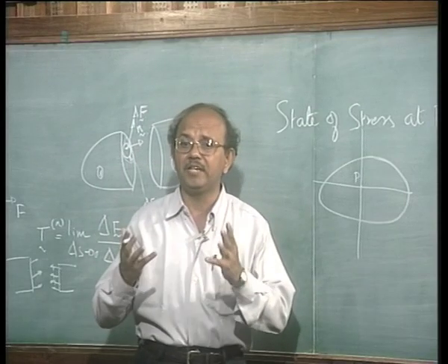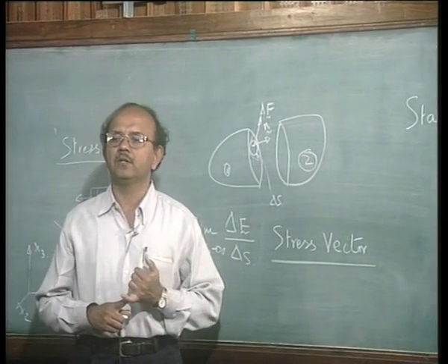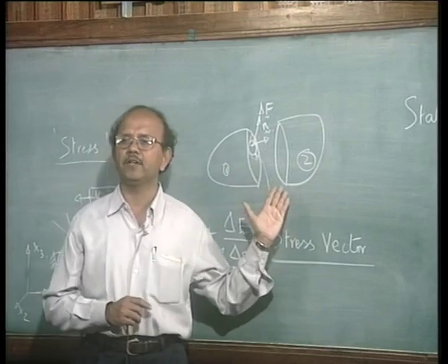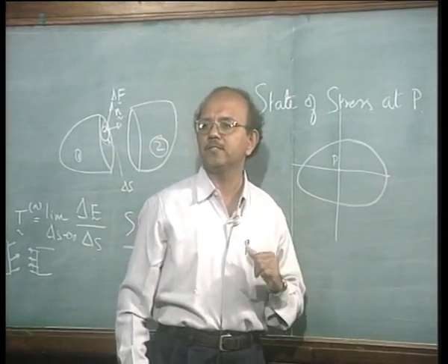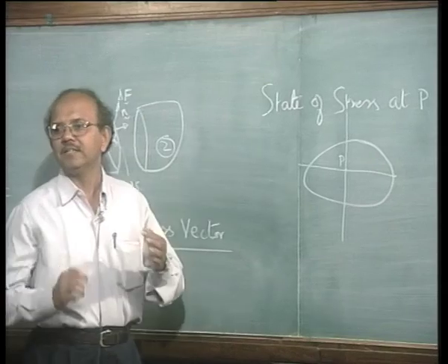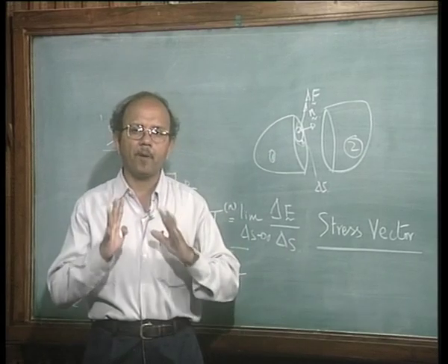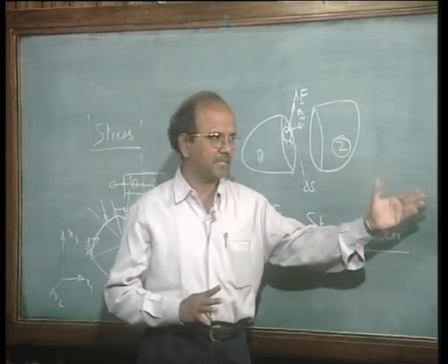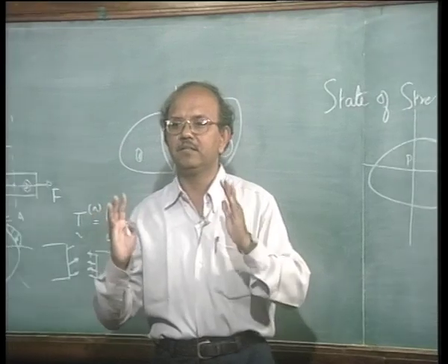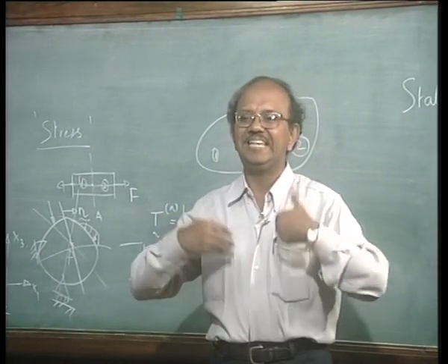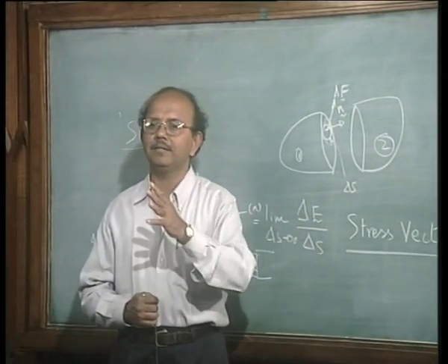So these 3 planes are well defined planes, okay, and the first thing I will do is, I know that it is difficult to define it in infinite number of planes. So as a first step, let me define them in these 3 planes. It turns out, as we will see, that these 3 planes are very useful to us, because if I properly define stresses in these 3 planes as I am going to do now, then it is possible to relate these stresses to any other plane that you would define by means of a normal n.